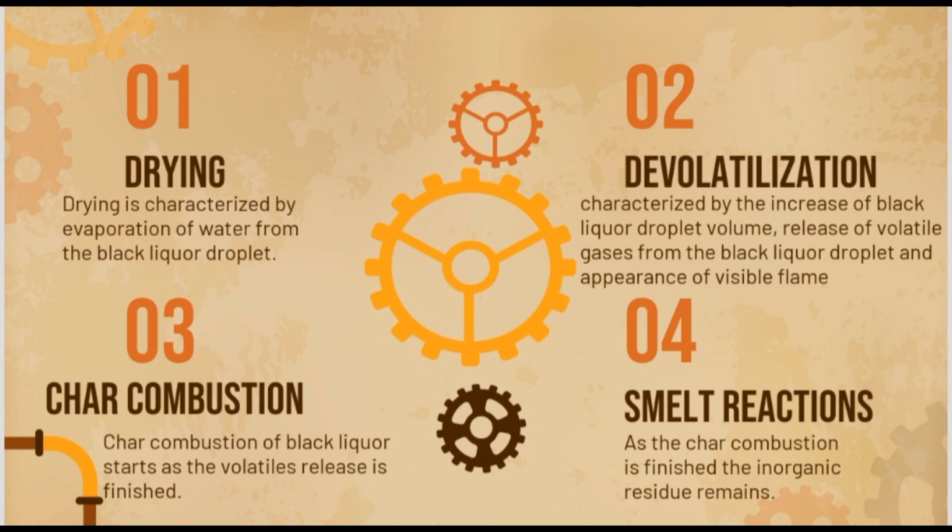The second is devolatilization. As black liquor dries and temperature increases, reactions with the lowest activation energy start taking place. For organic fuel, release of low molecular weight component gases such as methane, carbon dioxide, hydrogen, and hydrogen sulfide starts.